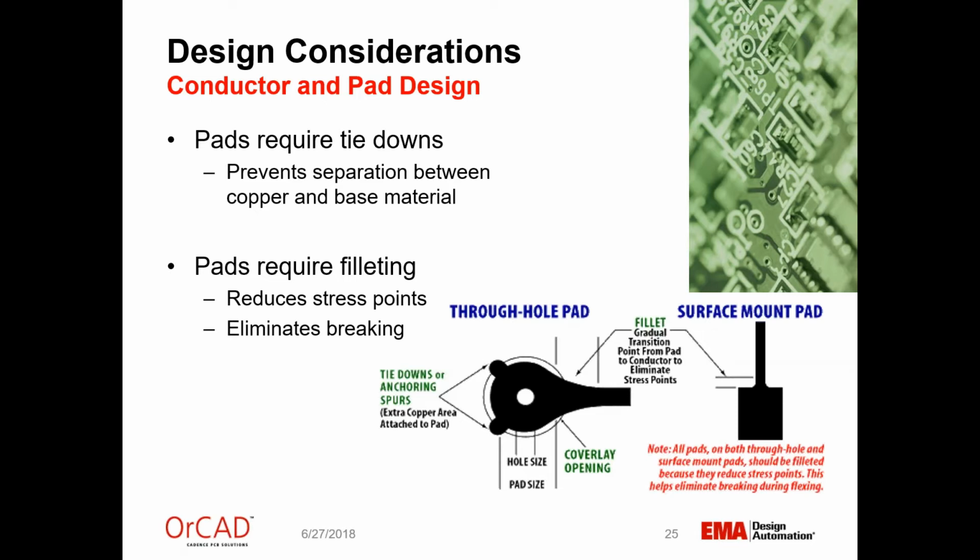This prevents separation between the copper and the base material. Also, all pads should have fillets, as fillets reduce stress points and help prevent breaking and cracking during flexing.